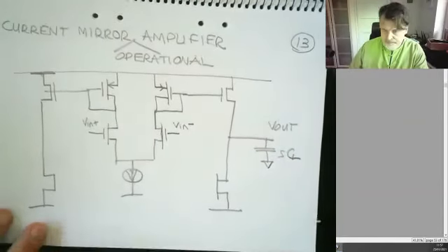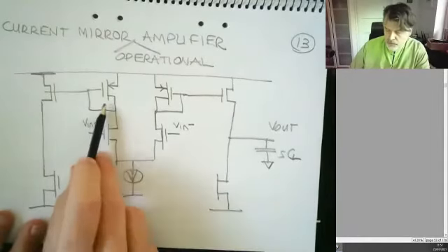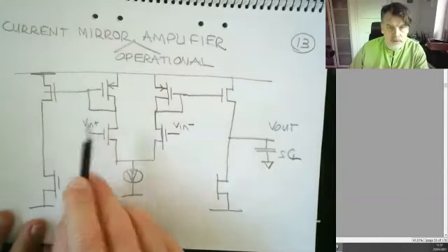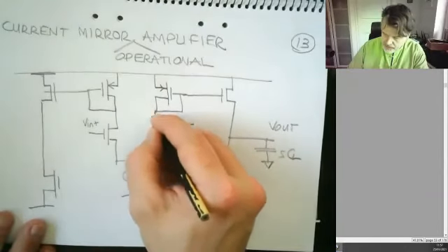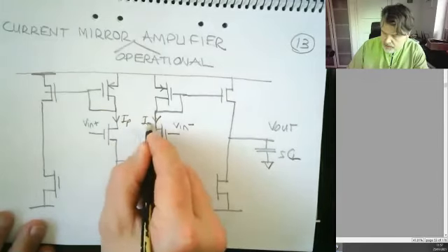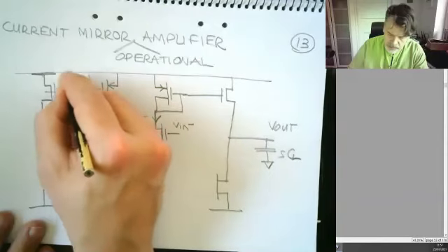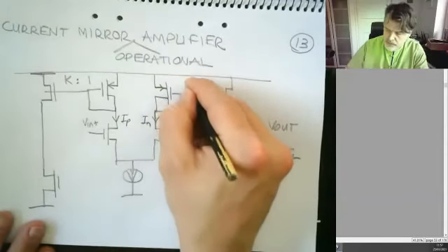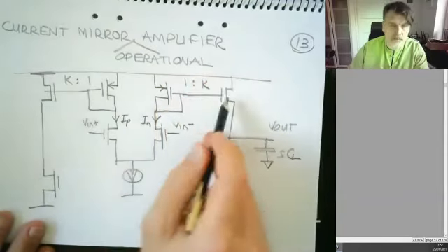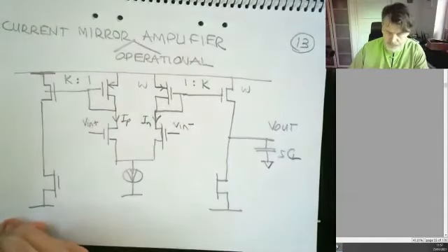load capacitance. So I put two current mirrors at the top here. So whatever current I have here, IP and IN, is now mirrored with a certain ratio 1 to K, for example, dependent on the sizes W and L for these guys that you pick.